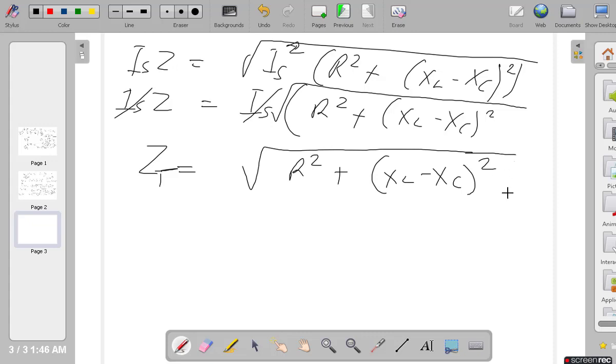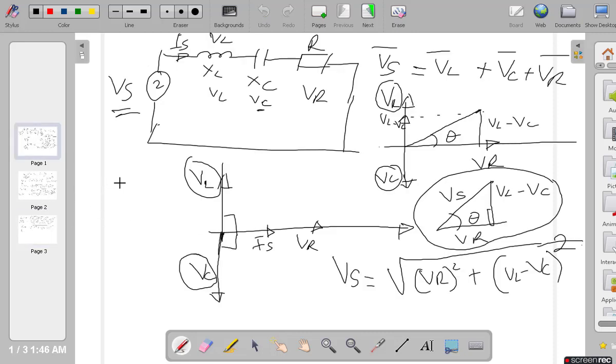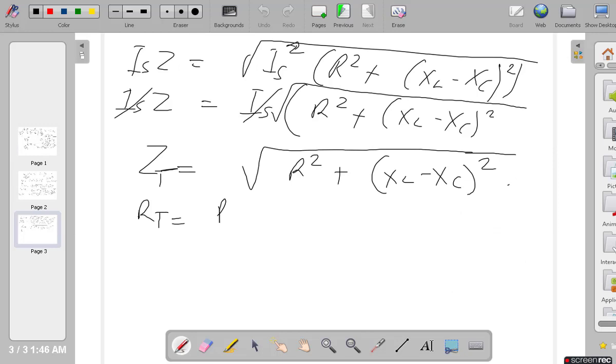So now guys, you can see for yourselves that finding the total impedance of the circuit is not as straightforward. To find the Z total is not the way we did it in a resistance circuit, where we found the R total. For R total in a DC circuit, all we did was add R1 plus R2 plus R3. But now in an AC circuit, we also have to consider their vector orientations. In other words, we can draw what we call the impedance triangle.